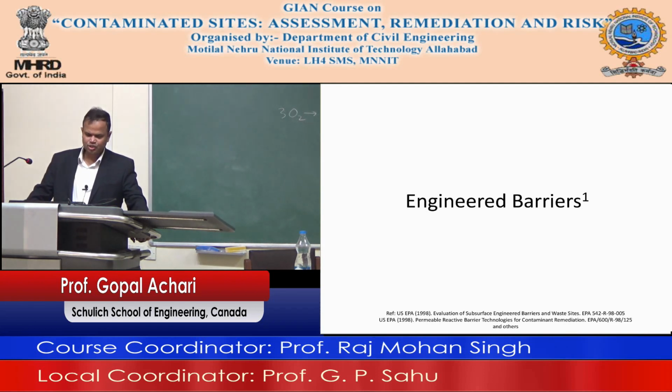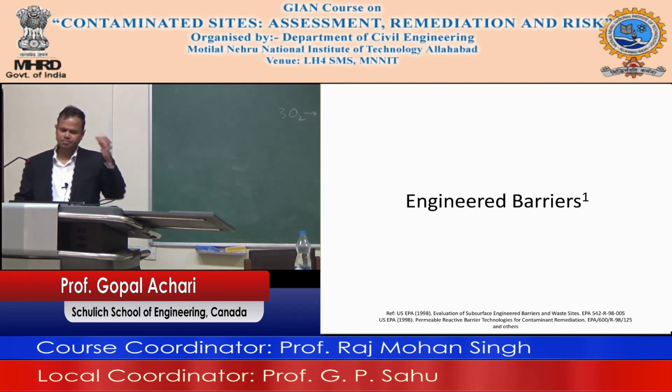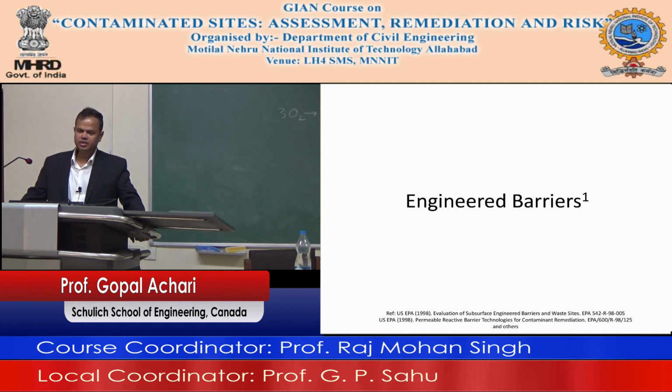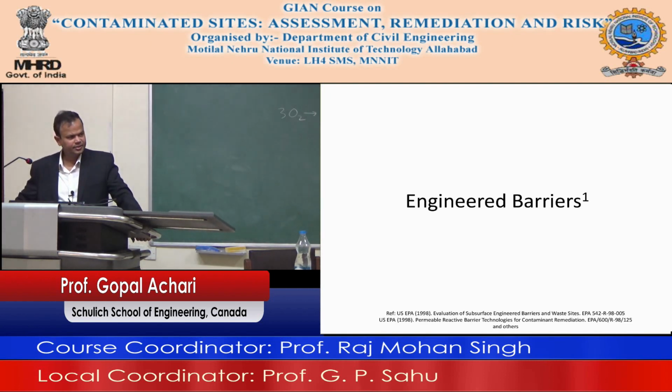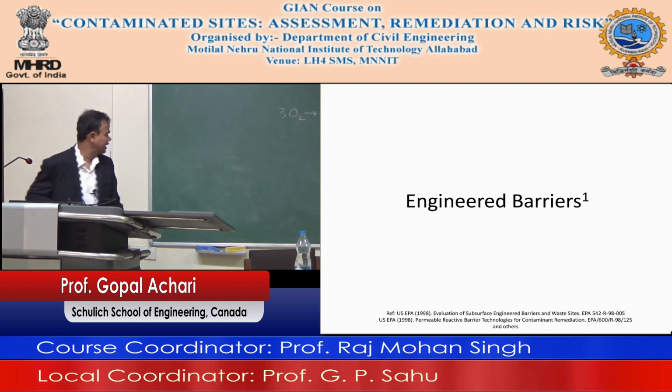Engineered barriers. Remember, the purpose of risk management of a contaminated site is to minimize the risk. If you can minimize the risk that a site poses, you might get a lot of flexibility from your regulator, the pollution control boards, with regards to how much time you have and what you want to do. One of the ways to minimize risk is what is called an engineered barrier. So an engineered barrier, so if I have